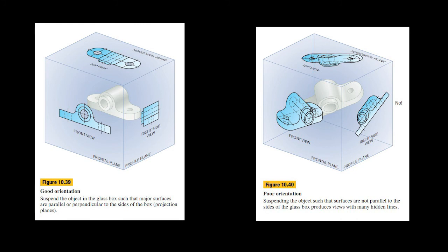You'll observe some hidden lines in each of these diagrams. We'll go more in depth into the hidden lines in lectures further into the series, but just for your information, hidden lines are used to represent features that are found on the inside of the object and not really on its exterior surface. A very common example of a feature that is generally depicted with hidden lines is a hole.